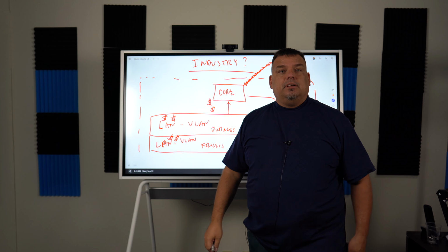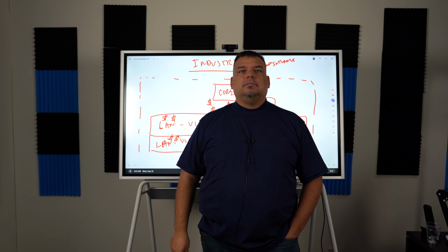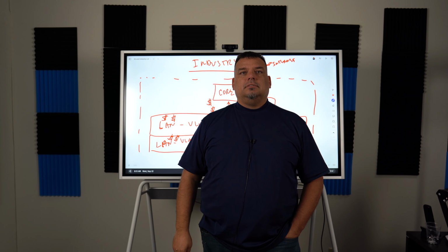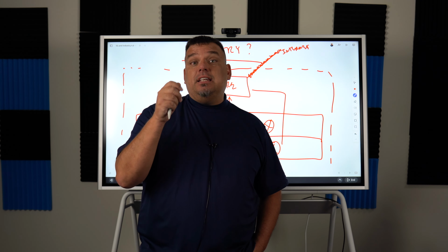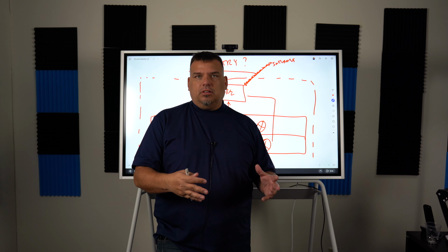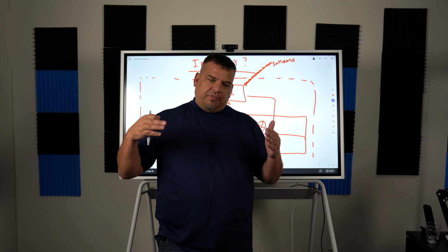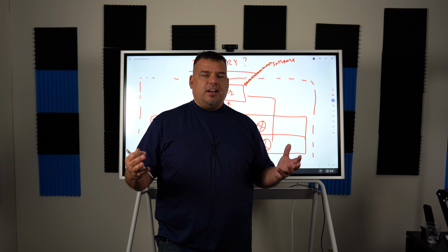Zach: So the question that the audience will ask is, will this replace my LAN? Or will there still need to be applications where LAN connectivity is necessary? Because of the redundancy within the network, can I start doing process control? Do I need a LAN still? So I would say this. The real implication for 5G is going to be in data transfer, but it's not going to be in control. Control is still going to be physical. It's still going to be physical networks with physical cables plugging into the PLC. That doesn't mean that the PLC isn't going to support 5G connectivity, right?